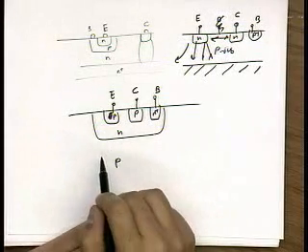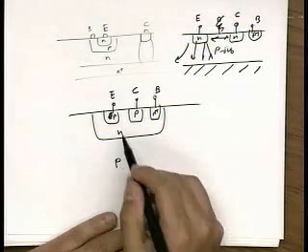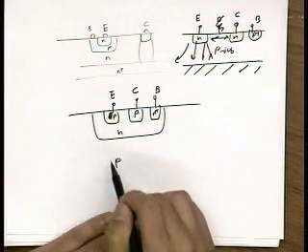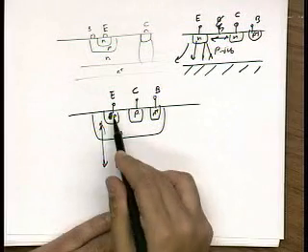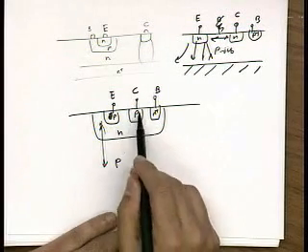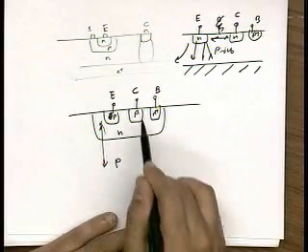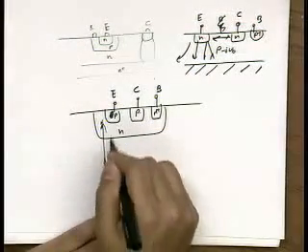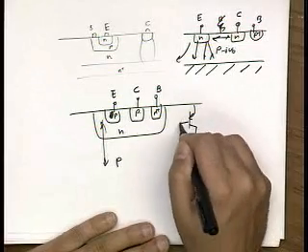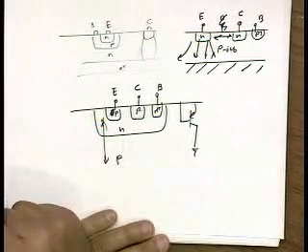basically, if you look at this picture, you see that the situation's really no different, because now I can either have a PNP device in this direction, or I can have a PNP device in this direction. And certainly this is going to capture more carriers, holes in this case, than this little junction is, right? Even if I completely surround this junction, there's still much more area going vertically. So I end up getting a vertical substrate PNP rather than what I desired, which was a lateral PNP structure.